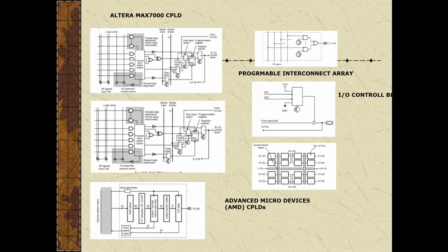For connecting the blocks together, all the connections in a Mach 4 between one PAL block and another are routed through the central switch matrix. The device can be viewed not only as a collection of PALs but also as a single large device, since all connections travel through the same path. Timing delays of circuits implemented in the Mach 4 are predictable.